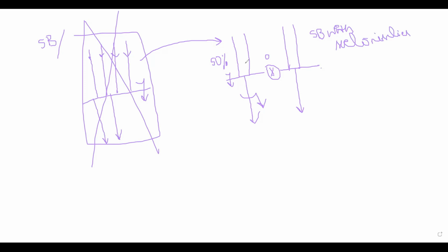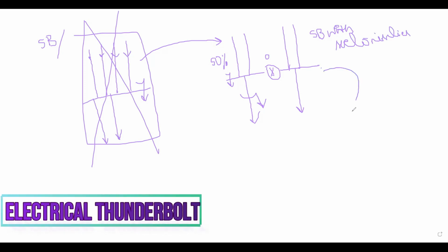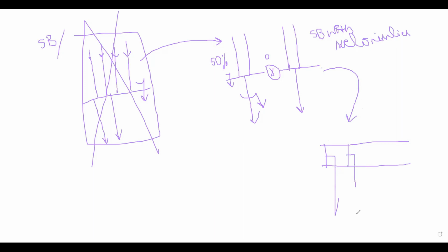And to avoid this 50% shutdown also, one more scheme was developed, that is the double busbar scheme, where four incoming lines are connecting to two buses, and these are the two outgoing lines. These are connected with the help of isolators. Now, generally both buses will be in open or in the closed position, so the power will be shared on both and it will go to this.